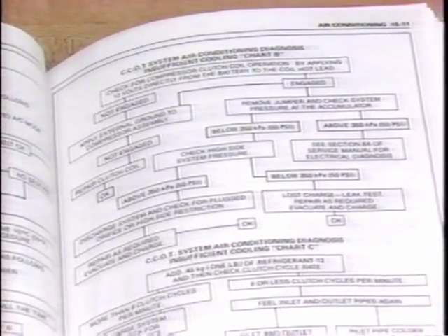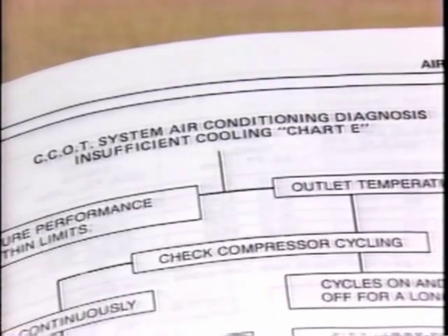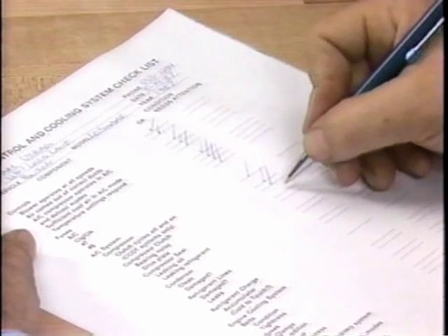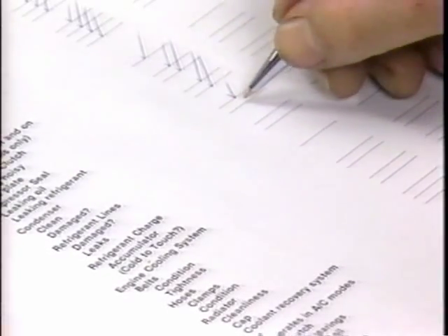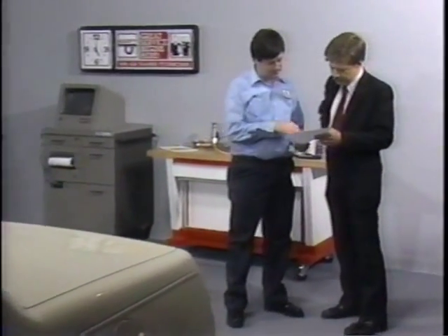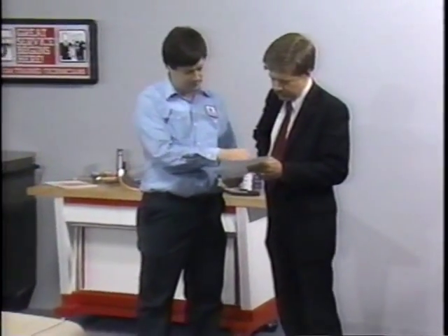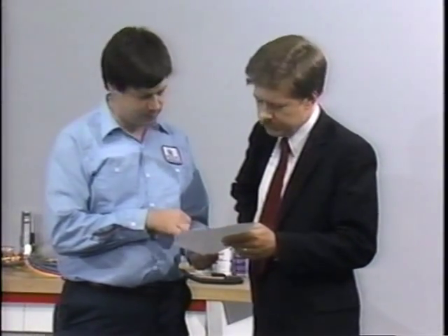The specific diagnostic procedures vary from system to system, but some basic rules remain the same. As with all diagnostic procedures, you want to make the best use of your diagnostic time by performing the easiest procedures first and eliminating as many possible causes of a problem as you can with each procedure. This checklist in your know-how reference book will help. Also, use the checklist when performing an air conditioning checkup and give a copy of the results to the customer. It's in a separate section of the book so that it can be reproduced easily.